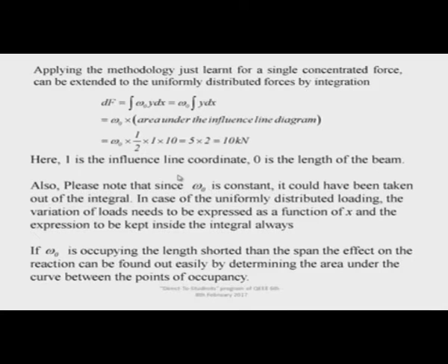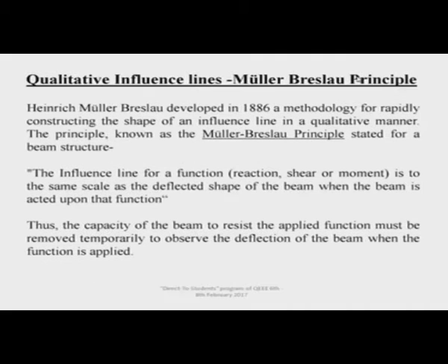A caution, none of the books discuss how it is when it is non-uniform. Nothing, you just express it as a function and integrate it, no problem, you will find the effect. And another, one of the very powerful methods in mechanics, and the most powerful method while drawing influence line diagram, is the Muller-Breslau principle. It is to be understood today itself for going to the next 3 sessions successfully.